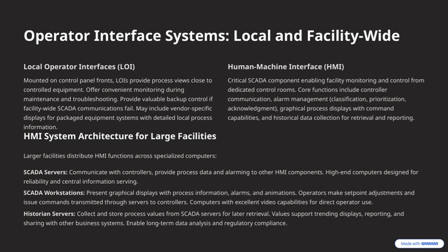In larger facilities, HMI functions are distributed across specialized computers to improve efficiency and reliability. This setup allows for dedicated control rooms that handle critical SCADA functions, such as controller communication, alarm management, graphical displays, command execution, and historical data collection.